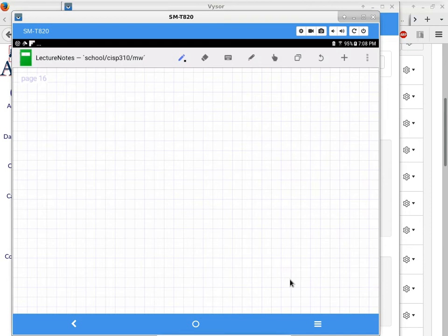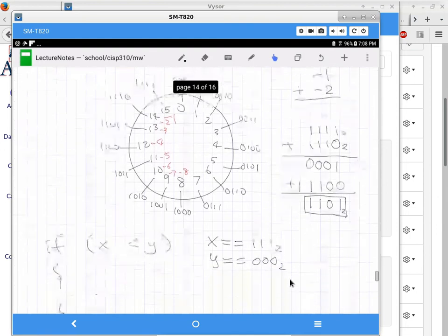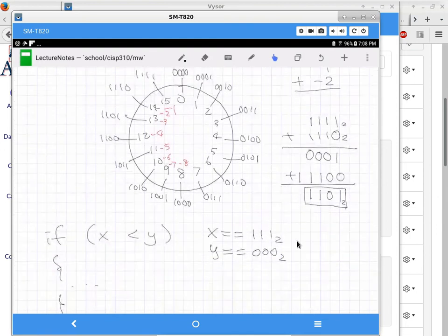I just have a quick question as to what happens to the carryout. Okay, so carry out, that's a good, legitimate question. So the carry out, which is this one bit here, is not a part of the sum. When we specify a 4-bit adder, the input numbers are 4-bit wide, but so is the sum. It has to be 4-bit wide. So that one extra carry is what we call carry out. It is useful in some cases. For the most part, at this point, we're just going to say, okay, this is the extra carry.